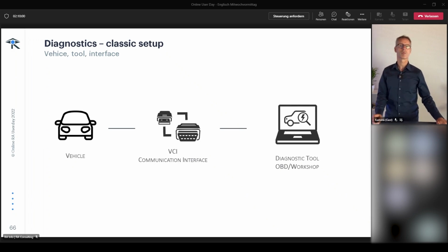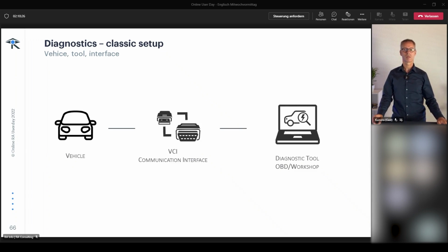By the way, what's the difference between measurement and diagnostic? We also have some measurement tool that Hanuman showed you before. The main difference is that measurement is like spying things or reading out some data that are already there. So just listen to the car for things that happen anyway in the car. Diagnostic is some kind of different. Commonly when you are doing diagnostics, you are having active requests to the vehicle or to the ECU, and also get some explicit response from the vehicle, either a one-time response or some kind of cyclic response from the vehicle.